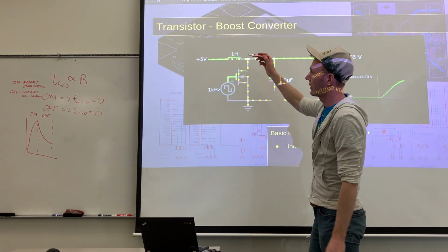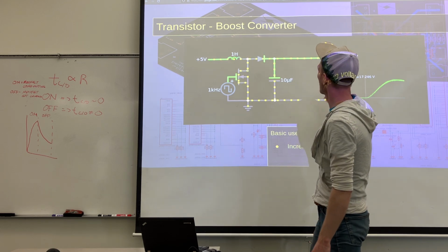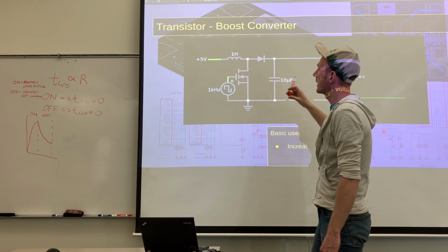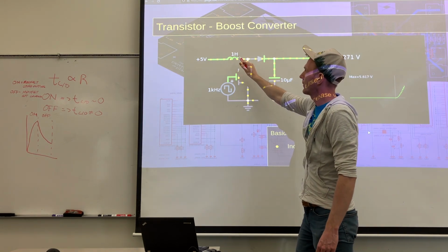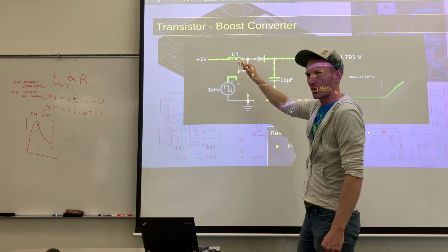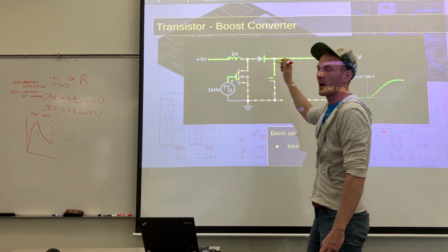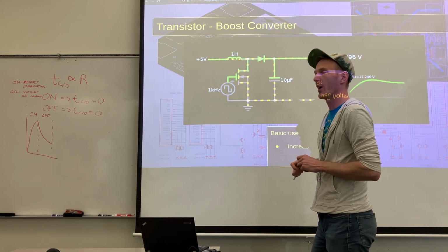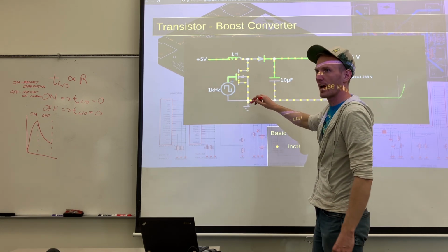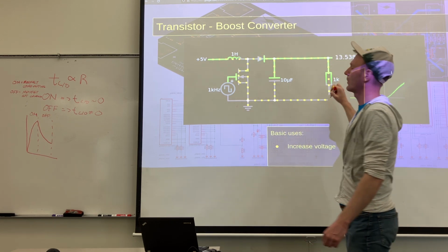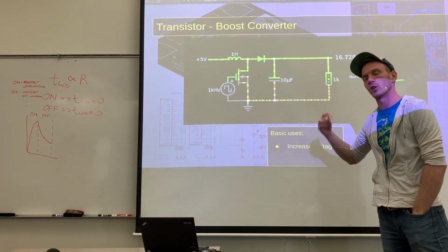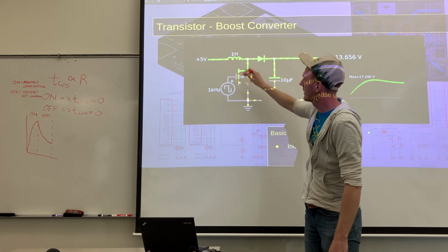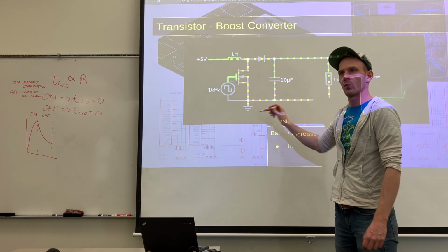When it's off, the path for flow is through this capacitor, which is going to begin to charge up. In addition, this thing was once at really high current, but it's now getting less, like it wants to be at a lower current from where it's been. So your flywheel, you've spun it up ridiculously fast, but the new equilibrium with the resistor in there is spinning a little bit slower, lower current. Like imagine if this inductor wasn't here: insanely high current, not so much current, right?